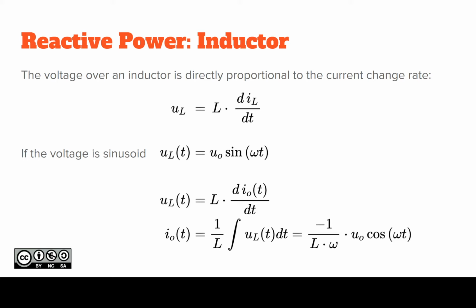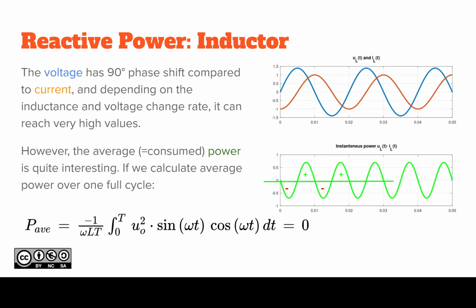Anyhow, if you have some frequency signal, then it shows that the lower the frequency, the more current. The higher the frequency, the less current. So it blocks higher frequency current from passing. Same stuff as we got the other way around on our RL filters. And similar to the capacitor, we again have the phase shift between the current and voltage. 90-degree phase shift. Now it's just in the opposite direction.